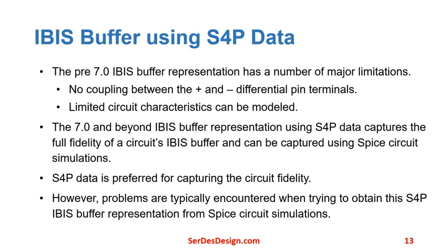The pre-7.0 IBIS buffer has a number of major limitations. There's no coupling between the plus and minus differential terminals. There are limited circuit characteristics for modeling.